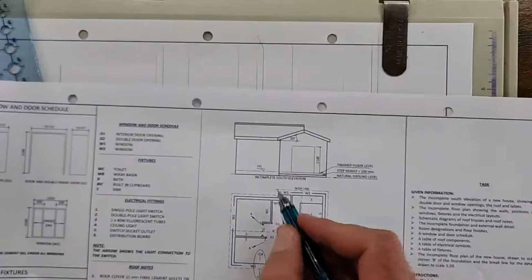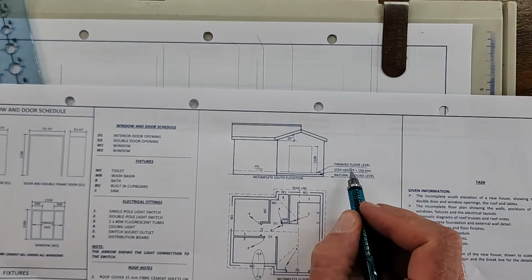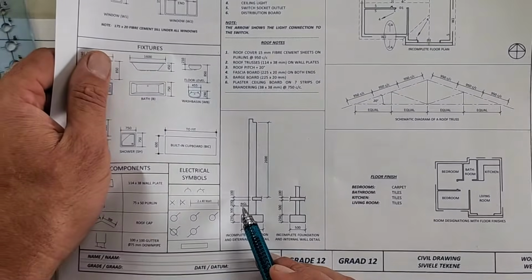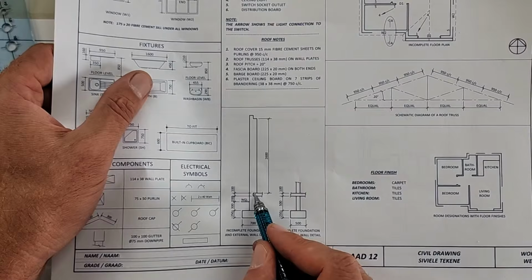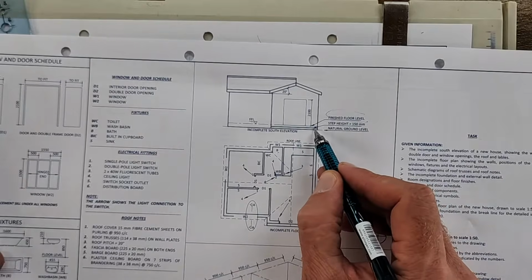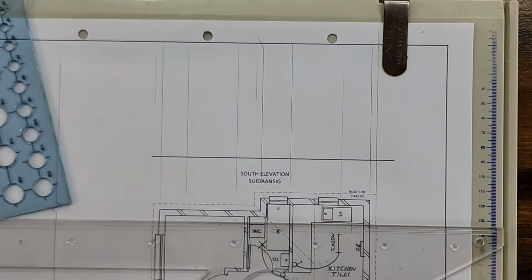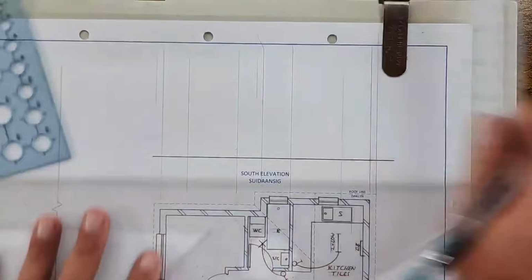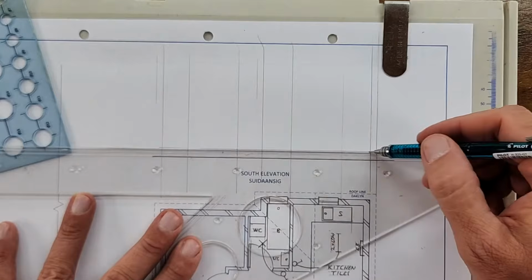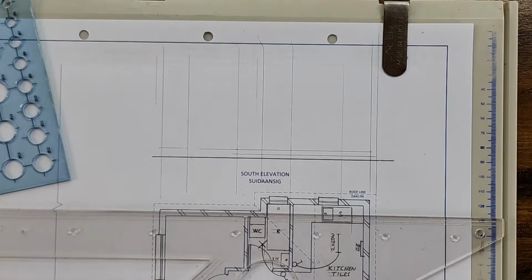Okay, that's that line that you see at the base here, and I'm using this they say the first step, 150. The finished floor level height, they don't give it here, but it's going to be here. So I've got the natural ground level, that's that line. So 200 plus another 100, that makes it 300 for the top of that finished floor level. So if the first one is 150 and I need to get to 300, it's going to be another 150 there. Then I'm at finished floor level. So again, scale 1 to 50. We're going to go 150, 300. Okay, and just first of all, just do a construction line all the way through. There's my step. I can draw that all the way through just in construction.